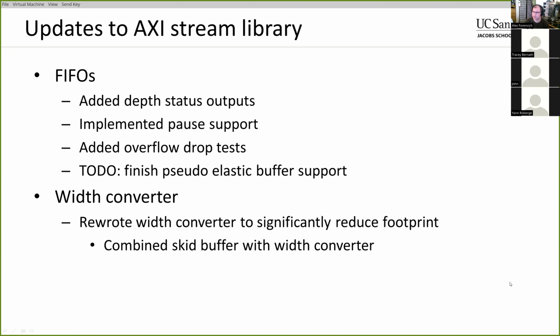I've also been doing some reworking of the test benches of the FIFOs. Did a bunch of reorganizing and adjusting to try and get some stuff cleaned up, and I added some overflow drop tests. So this is for the FIFOs when used on the RX side, since they can't exert back pressure against the MACs. I mean, you can't really exert back pressure against the SerDes. It's just, you start getting data and you've got to deal with it. If you get into a situation where the RX FIFO fills up, well, it has to start dropping packets, and you want to do that without corrupting packets and whatnot. So I added some tests to actually test that functionality.